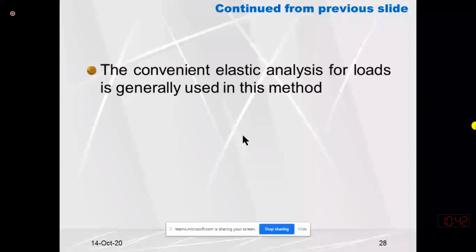It means if I am using the material strength equal to 0.9 Fy, I am still in the elastic range. So all the theory of elasticity and elastic formulas, for example, the shear formula, bending formula, and deflection formula, are applicable for the analysis and design of structures.